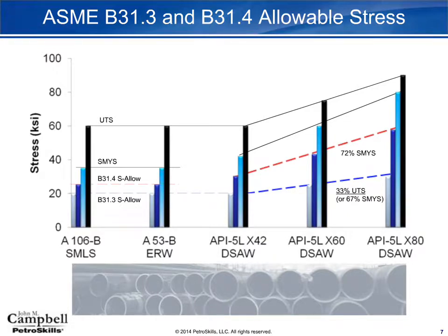Also, when you think about the utilization of pipelines versus process equipment, we can see far harsher infrastructure in refineries. There's a lot more expansive stress, and that cyclic behavior brings down the allowable stress. And that is, in part, the reason that we see lower allowables in B31.3 versus B31.4. I have an interesting example later on that really communicates the massive difference in safety factor between the codes and why we have high yield materials in pipelines rather than in facilities.